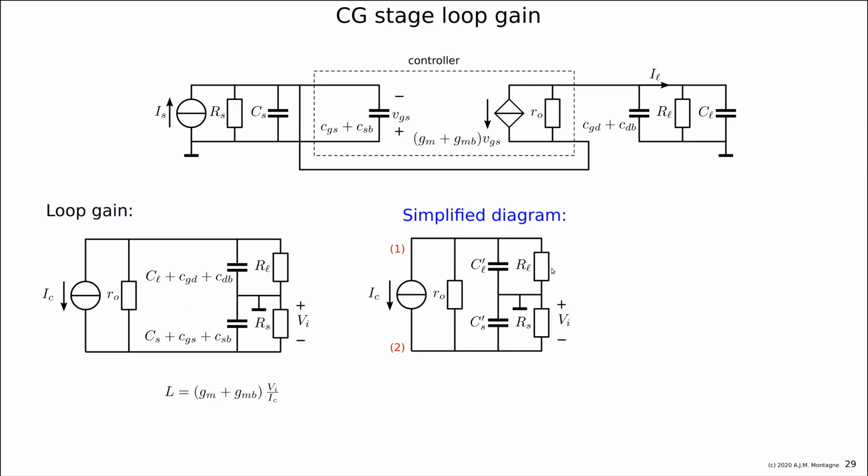and our assumption that if the load impedance becomes infinite, that there's no loop gain, you clearly see. If you make RL infinite and CL 0, there's no loop and there's no loop gain. And if you short the source, then RS equals 0 or the total capacitance is infinite, then there's also no loop gain. So the loop gain strongly depends on the load impedance and of the source impedance, of course. And RO establishes a direct transfer.